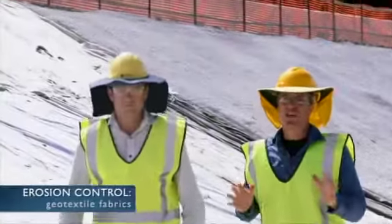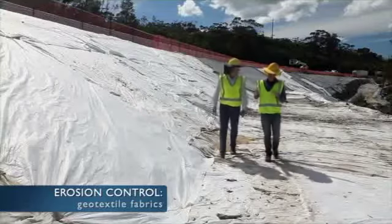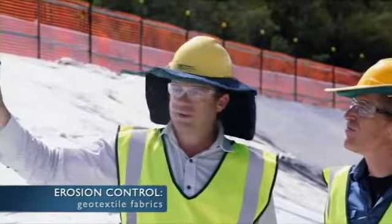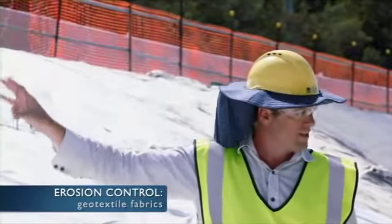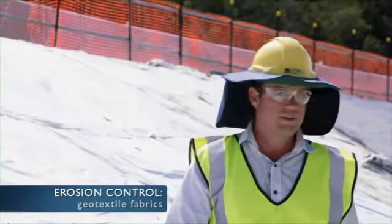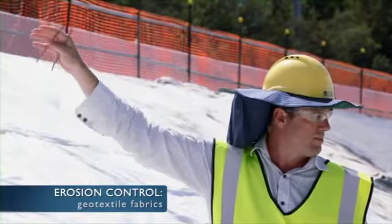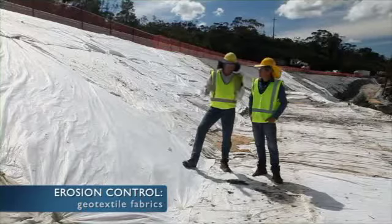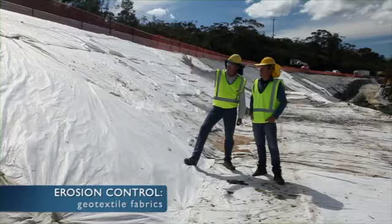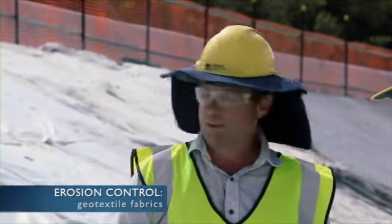So, starting with geotextile fabrics, which we have a great example of here. Now, Chris, I imagine you have to tie them down so they don't get washed or blown away. Yeah, absolutely, Pete. So what we want to do is make sure that water doesn't get under the geotextile fabric, which will cause erosion underneath it and make that control essentially useless. So starting from the top, we want to make sure we properly anchor that control in place by digging it in. Geotextile is held in place with large anchors, like this one. Yep. And as you can see, as it comes down the slope, the geotextile is lapped over the next one below it, so the water can flow over that without impacting the control.